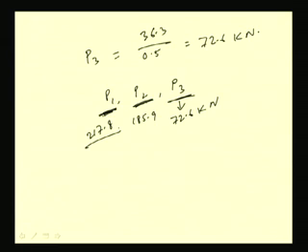That means, if we apply 217.8 kilonewton, the joint between girder and angle can take care, but the joint between angle and bracket cannot take it, because it can take maximum 185.9 kilonewton. So, this will fail if we apply this one, as well as the joint between bracket and column is also going to fail. So, the least of these 3 we have to consider as the permissible load.